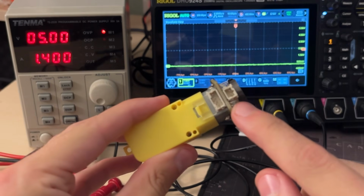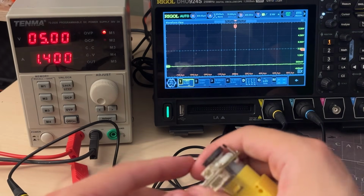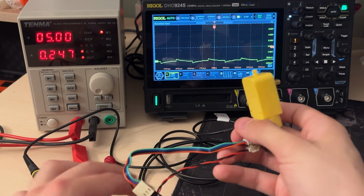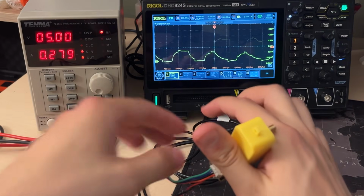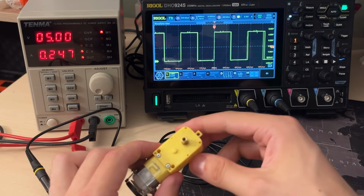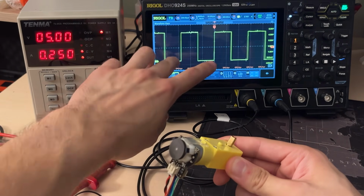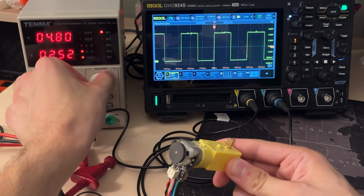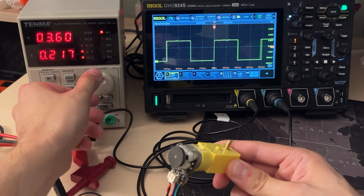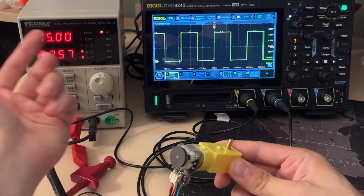So we have two connectors here, one is for power to drive the motor, and the other one is for the encoder. So if we wire everything up and turn on the power supply, let's take a look at the scope. There is some signal issue, but here you can see a perfect square wave. Now, why do we have two of these? That's because from here we can only see whether we are spinning faster or slower. So if I lower the voltage, you can see the frequency go down, which means the motor is spinning slower, and if we increase the voltage, you can see that the frequency is picking up, meaning the motor is spinning quicker and quicker.